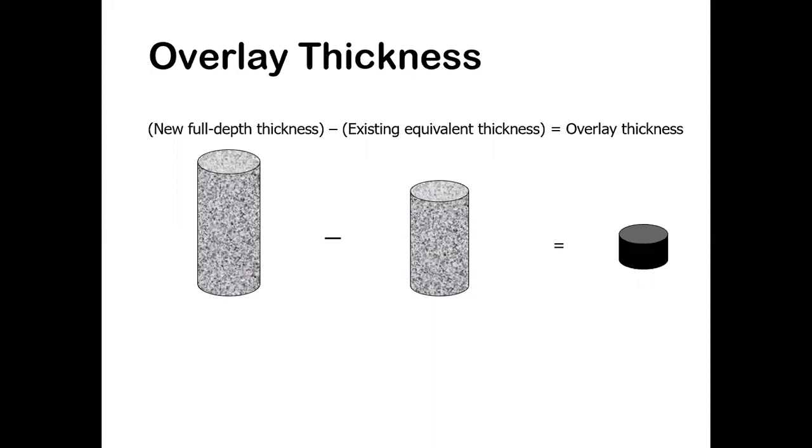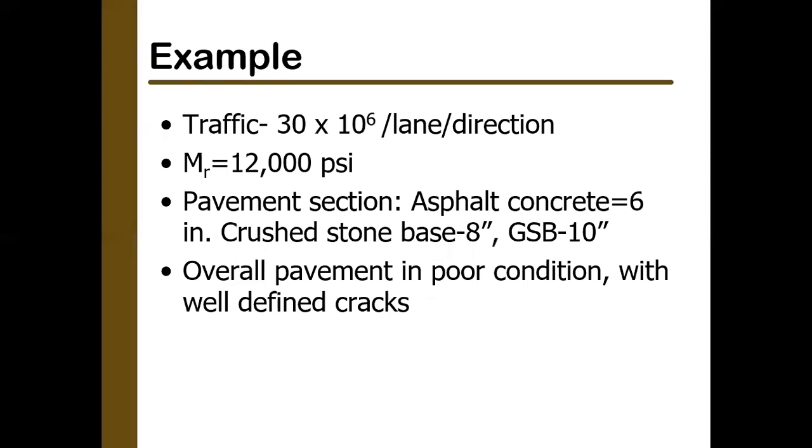Now, once you know the full depth thickness from the traffic and resilient modulus, you subtract the existing equivalent thickness from it to find the thickness of a new overlay. So let us solve an example to find the overlay thickness to explain how this method works.